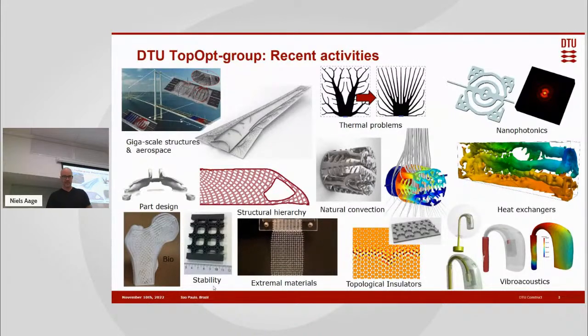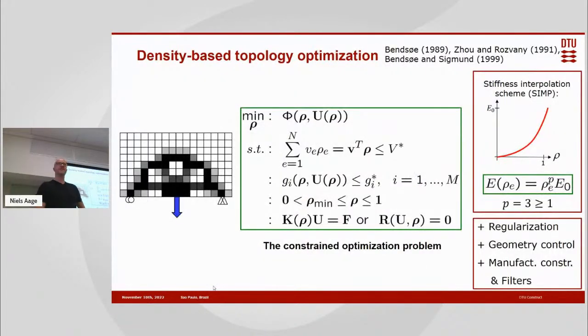And what do we mean by changing the design? Well, lots of methods exist to do that. You could do shape optimization, you can do sizing optimization, you can do topology optimization. And one way of thinking of topology optimization is like this: you just take some domain and then you ask every point in space, do you want to be material or do you not want to be material, such that we get the best performance possible that we're after while fulfilling a number of constraints.